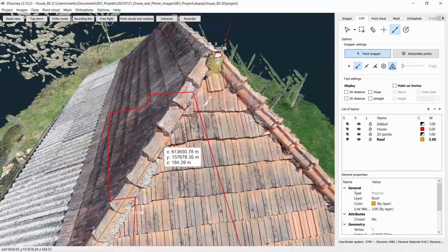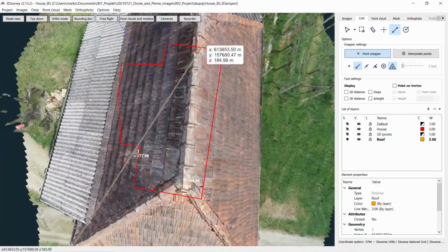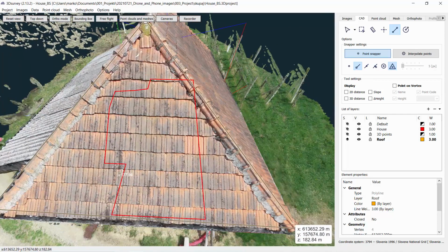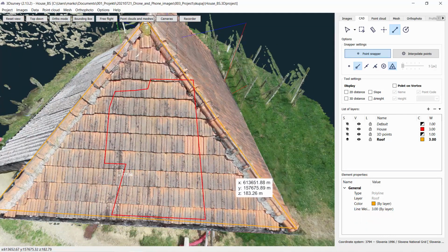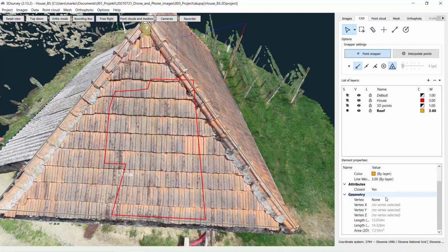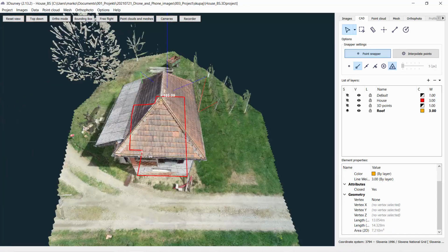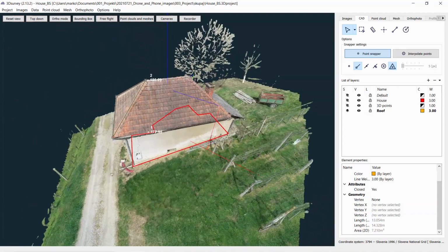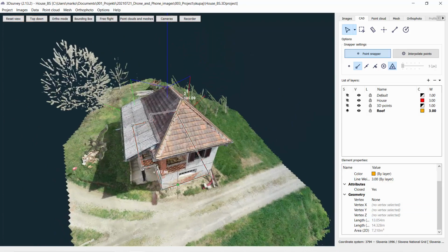Okay, I could create triangles so that later on you can easily calculate the 3D area, so that they know exactly how much material they need. I just draw one triangle. If I select this one, you also have here the 2D area of this triangle, which is available. Okay, cool. This is it. Most of everything.